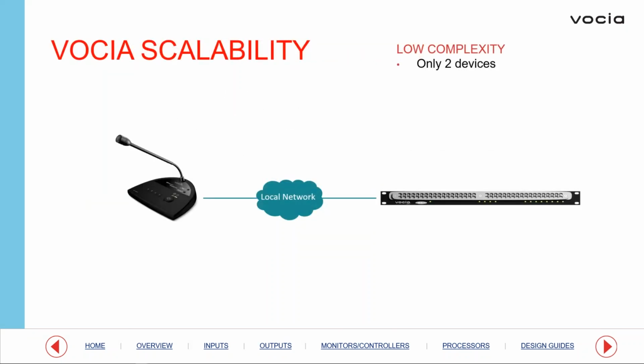So the one piece that we talked about earlier is that local network piece. So definitely we have to have a local network. A couple of reasons. One, that's how we transfer all of our information, in this case, from the paging station to our amplifier. Number two, because that paging station is seeking PoE through that category cable. So that's how it comes to life. So yeah, there's the network piece, and we've discussed that. But literally, that's your system. So that local network would be that PoE switch that we showed in the slide before, and very low complexity, very scalable. So that's how we start.